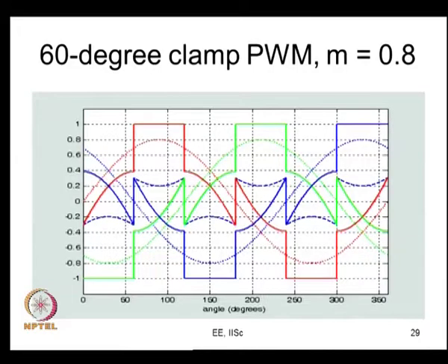How do you actually evaluate the conduction loss? The same procedure. Now, the duty ratio is given by, if you have this modulating signal, and that gives you the duty ratio. The duty ratio is 1 here, the duty ratio is 0 here, and this is 0.5. So, if you use these duty ratios and substitute in that expression, it is possible for you to calculate your conduction loss.